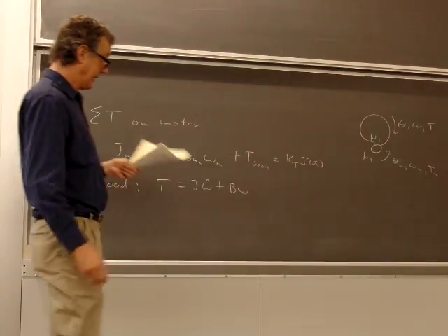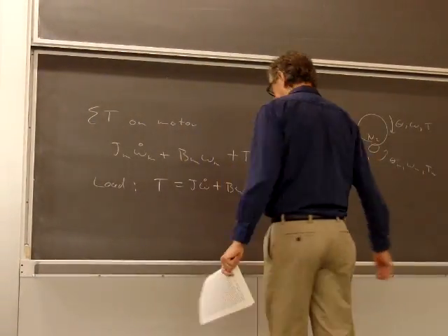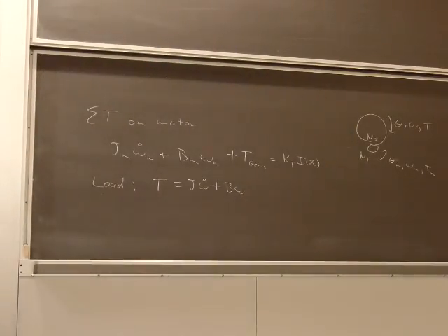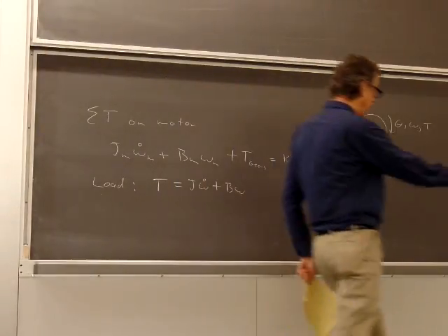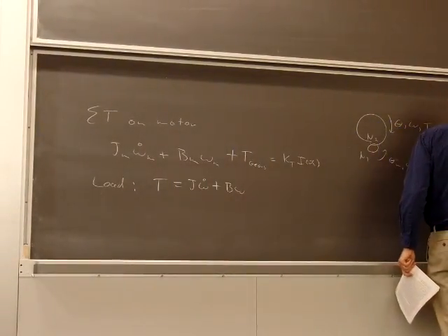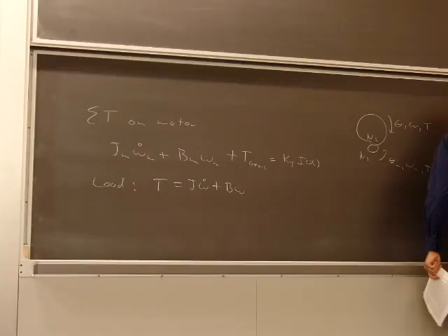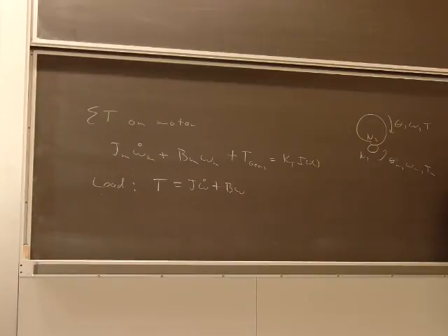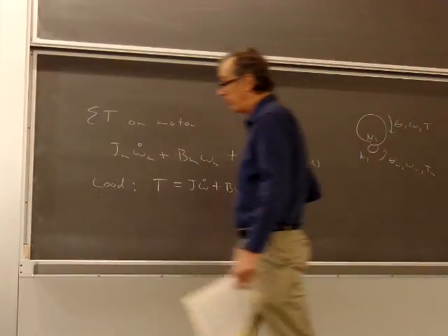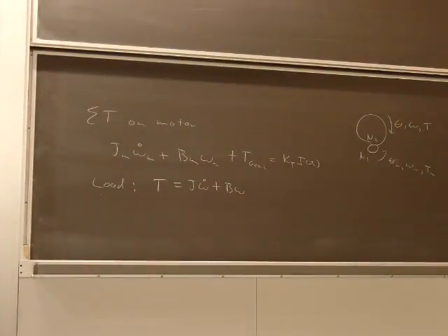And combine all these things. So what I want to eliminate are these variables. So I substitute in for those in terms of theta. Everywhere I see a theta M, I'll put in N2 over N1 theta. Every time I see a torque of the motor, I'll put in minus N1 over N2 T. Combine everything together, and we get our differential equations.